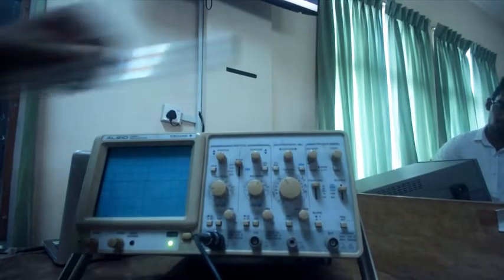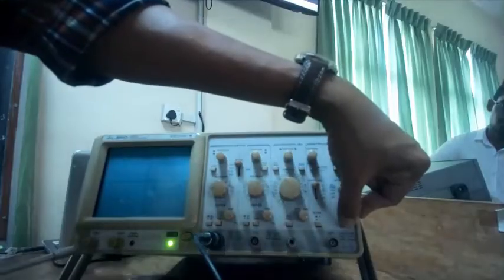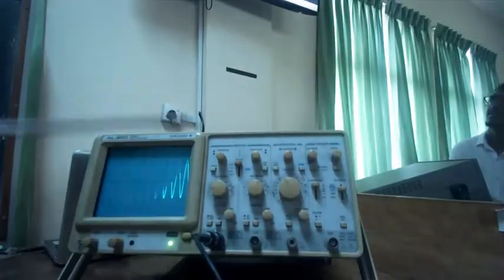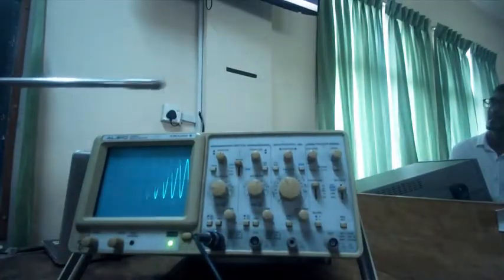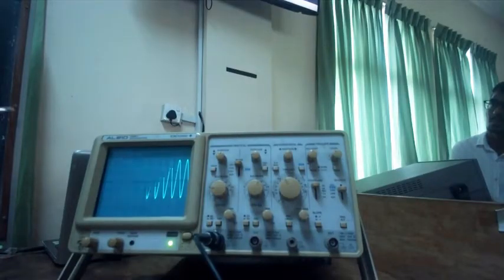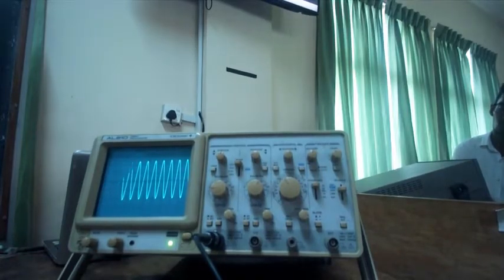Now if I press this button here, it triggers because it says alt, which means it changes the source alternately every cycle. You draw one, you look at channel 1 until it reaches that level and slope, and then trigger it. Come back, wait for channel 2 to reach that level. Alternately you go back and forth.